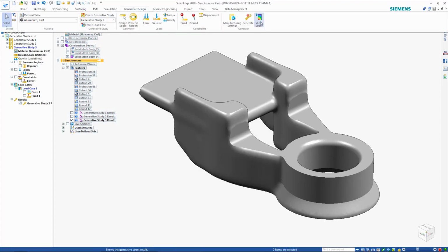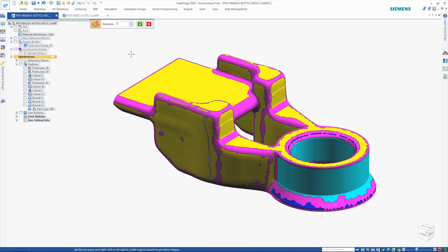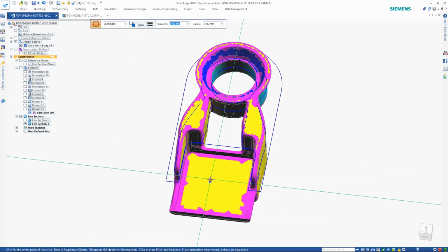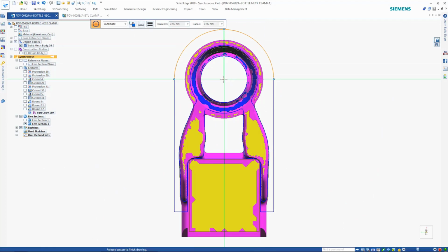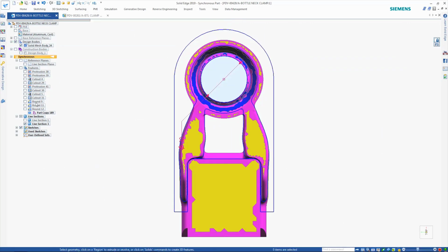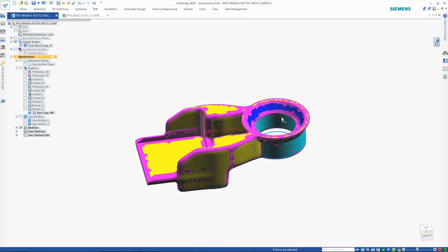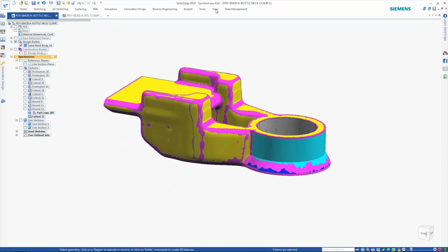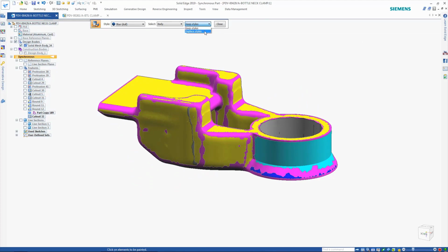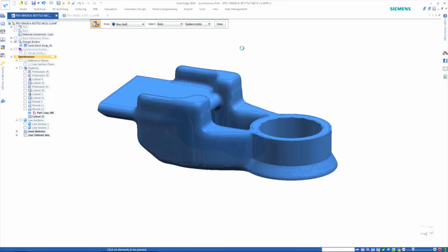The result from the Solid Edge generative process isn't just an idealized shape that needs to be reverse engineered. Siemens Convergent technology allows the use of mesh data downstream. Now Solid Edge will recognize planar and cylindrical faces on the mesh body. Here, a simple sketch on the underside face is used to create a cut to increase the size of the bore. The ability to combine mesh data with regular modeling features is unique to Solid Edge.